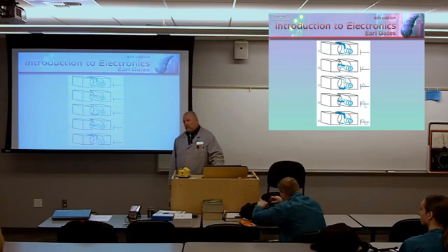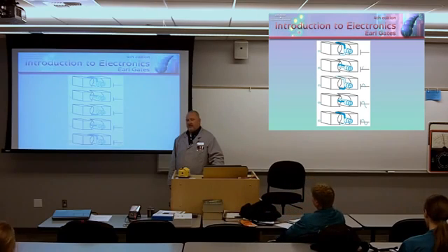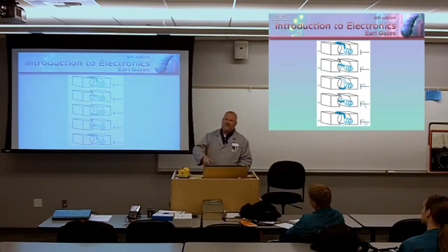So, your car, if your battery is totally dead, if you remove your battery and try to push start your car, it ain't gonna work. Okay? If your battery is kinda dead, not enough to crank the starter, but enough to go click, click, click, that's probably enough to create enough of a magnetic field so when you push the car, pop the clutch, start the combustion process, get the engine turning, immediately you're going to start to increase the voltage to these windings.